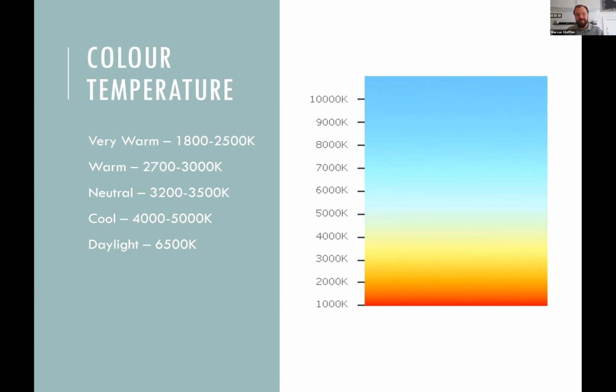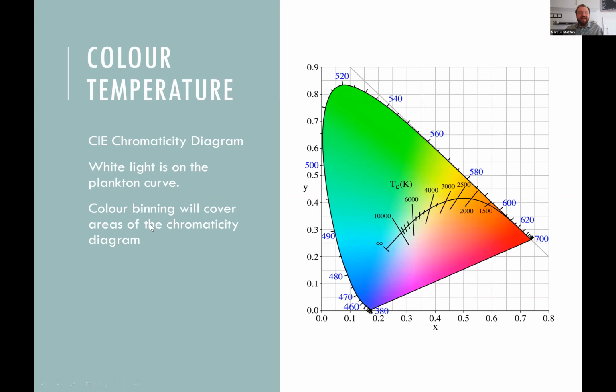And that can be quite nuanced in how you go about doing it, and it can mean that you have to do a lot of testing. You have to try it out on finished samples, make sure you get the right color temperature for the space. But it's not just blue and yellow lights. Actually, there's a whole range of different whites out there.